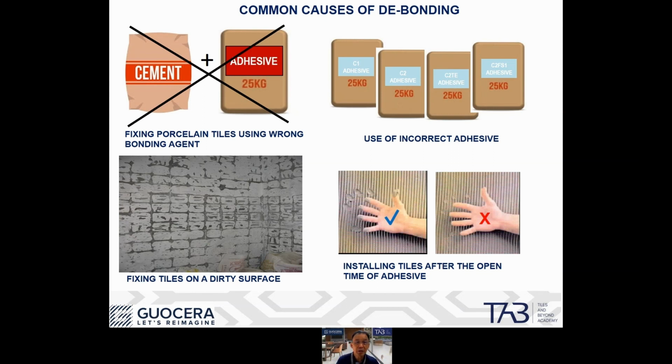If cement was used, even though the coverage was full, the tiles are going to fail. It doesn't mean that there's no void on the tiles. So there are many causes. The debonding and hollowness can be caused by any of the following reasons. I hope that answers your question.